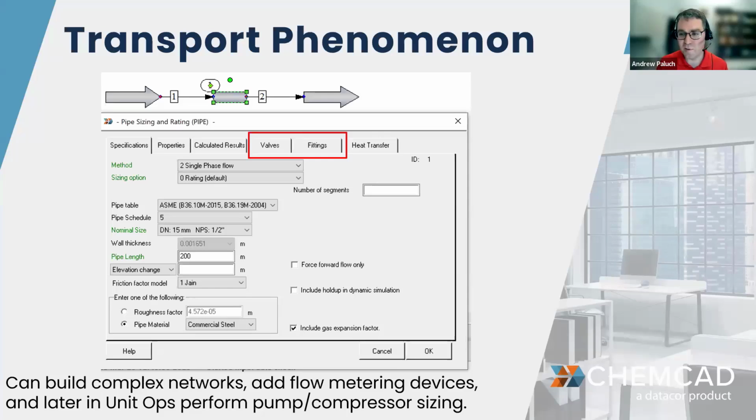This is just a simple example of pressure drop across a single section of pipe, but you could build this up. You could take your feed stream and have a divider, split it into 3 streams with even flow rates, send those to 3 pipes in parallel, and then bring those back and look at what happens with 3 pipes in parallel versus 3 in series, or 1 long pipe.